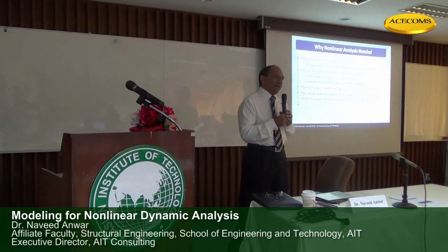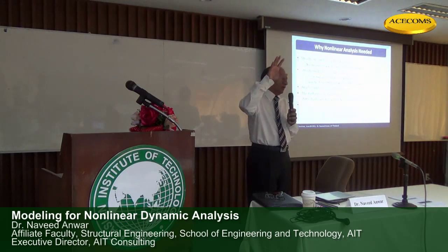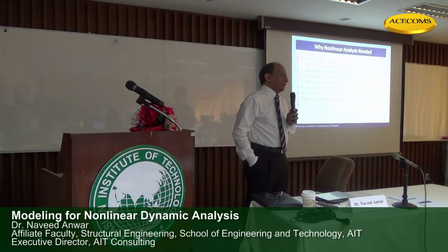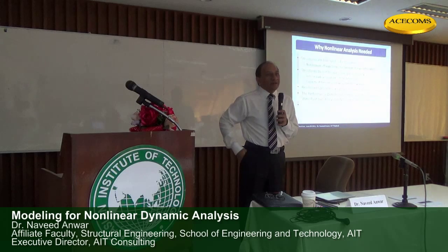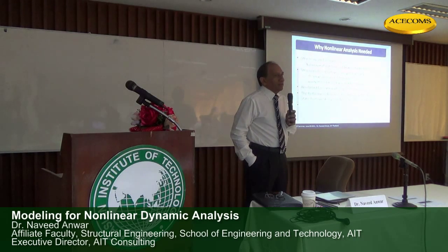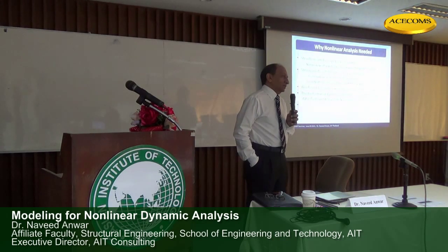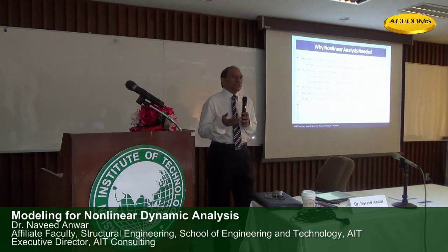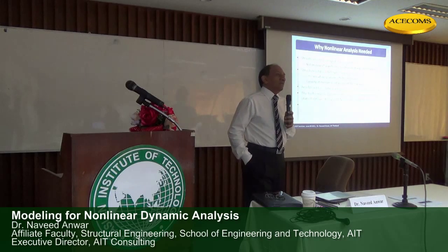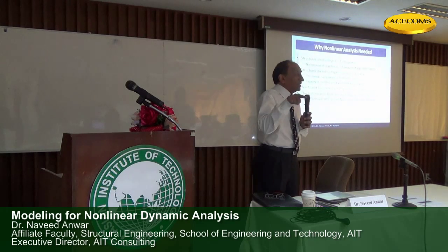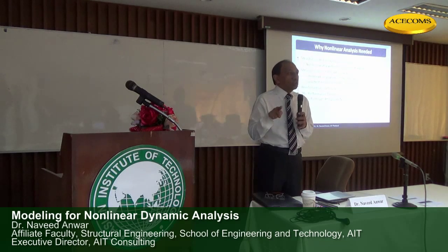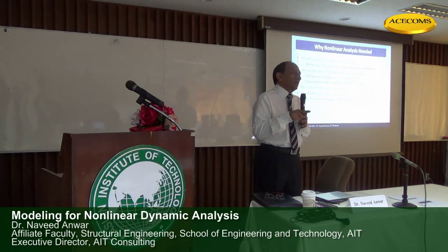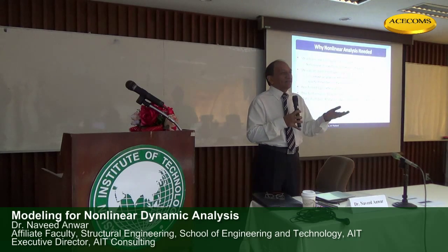If the structure behaves linearly, that means if I make a model of a small frame, 2 columns, 1 beam, and I apply a load of 1 ton, you do the analysis, you get a displacement of 1 centimeter. You apply 10 tons, you get 10 centimeters. You apply 100 tons, 100 centimeters. A million tons, a million centimeters. What does it mean? Can the structure take a deformation of 1 million centimeters? But your analysis will indicate that. So that means there is no check in the elastic analysis on the capacity. Whatever force we apply, you will always get the results.